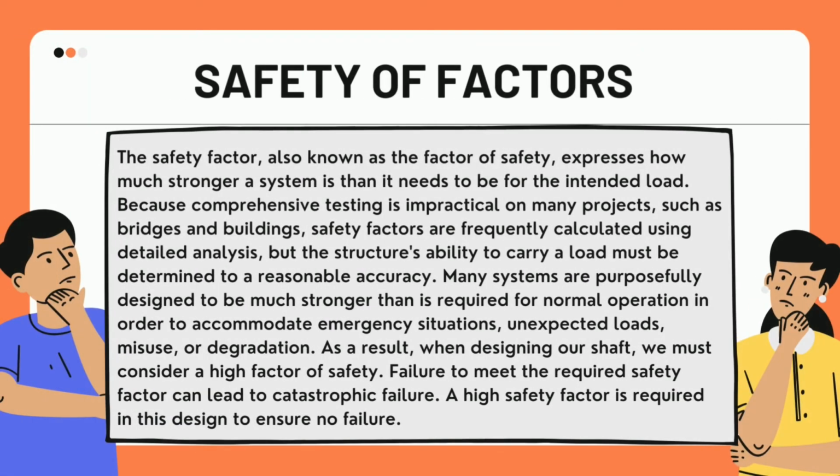Now the discussion part. In the discussion, we will talk about the safety factor. The safety factor, also known as the factor of safety, expresses how much stronger a system is than it needs to be for the intended load. Because composite testing is impractical on many projects such as bridges and buildings, safety factors are frequently calculated using detailed analysis, but the structural ability to carry a load must be determined. Failure to meet the required safety factor can lead to catastrophic failure. A high safety factor is required in this design to ensure against unknown failure.